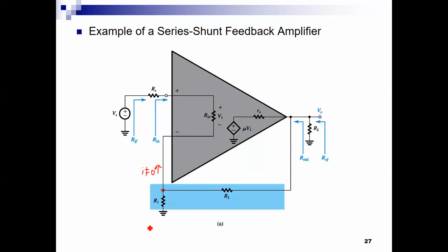In this picture, he is showing me in blue the beta block, and he is also showing me that for the full feedback amplifier, voltage out, as we said, is seen after RL, so ROF includes RL, and RIF is seen after RS like any amplifier, but RIF includes RS.